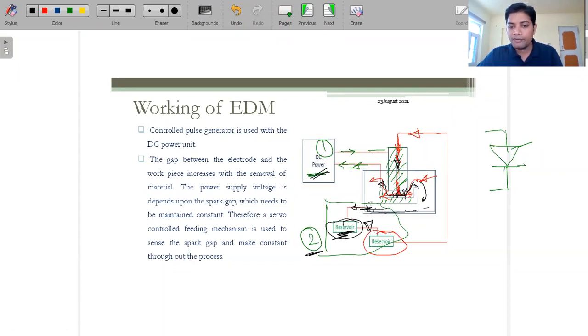And here we are using this filter. Why are we using the filter? Because the material which is removed, we do not want it to move again. If it moves again, there will be a lower wear rate, which means the advantage will become a disadvantage or demerit. We do not want it to create a hurdle for the next removal of material or the next spark, so we use this filter for the abrasive slurry. Okay guys, so this is basically the working mechanism.